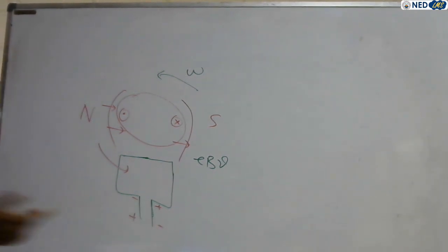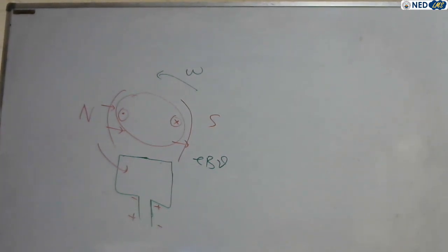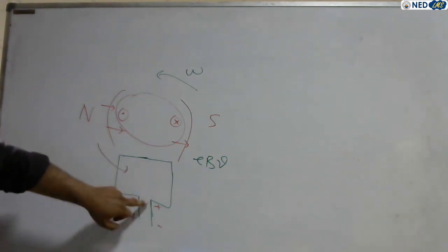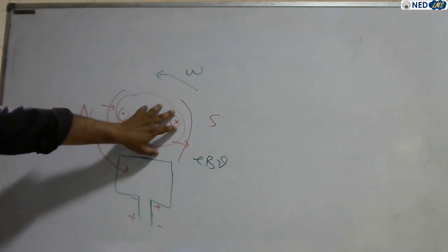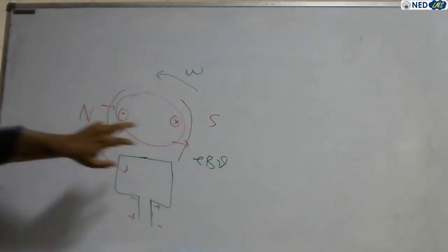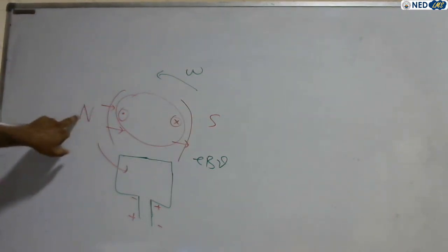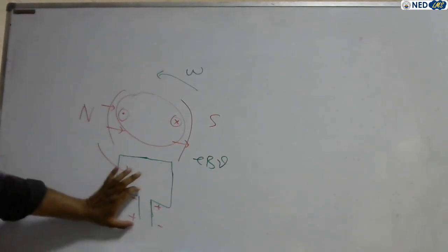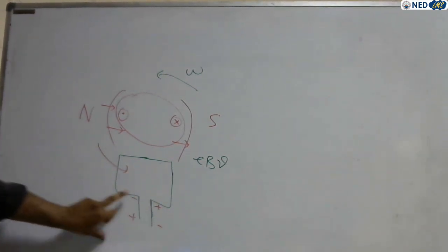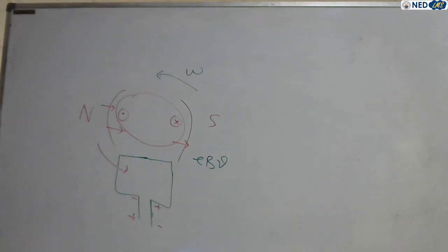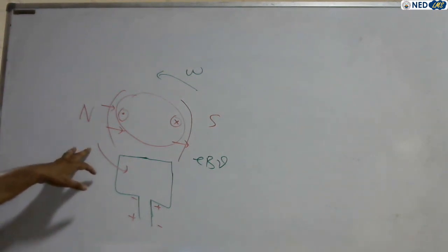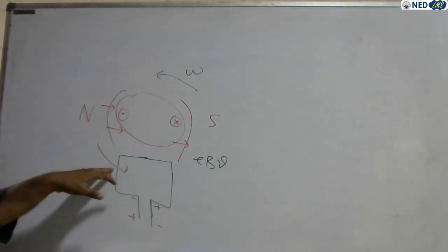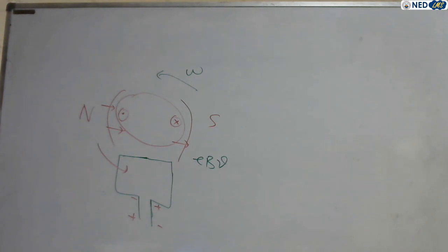So that's why the polarity in the rotational motion alters. Every time the rotor conductor moves, its polarity alters. When the rotor conductors are under the influence of the south pole, and when they are under the influence of the north pole, the voltage generated always alters. That means positive, negative, negative, positive. You see, the polarities alter in this way. I hope you understand. This is the actual motion of the conductor, the actual generation, in which you found the polarity of the generated voltage. So that's why your voltage alters all the time.